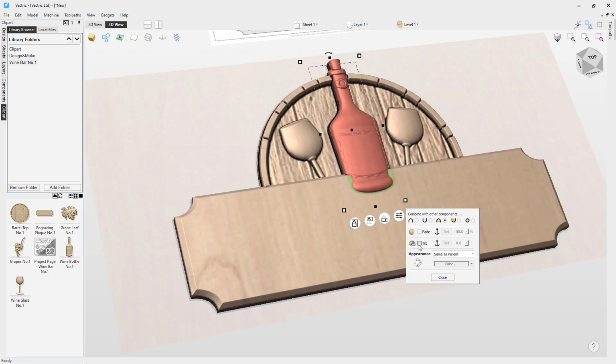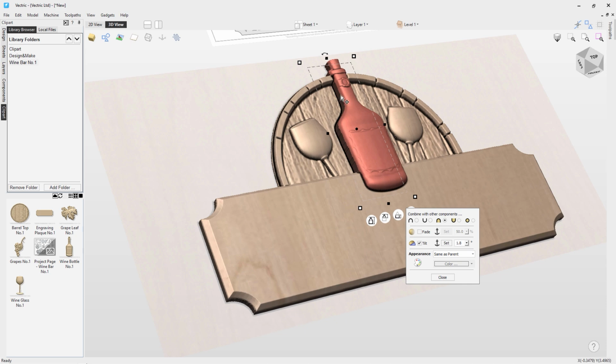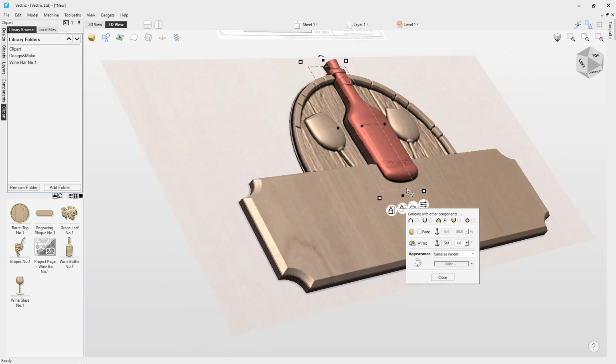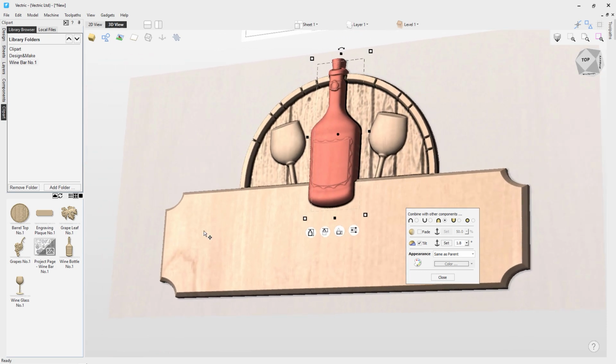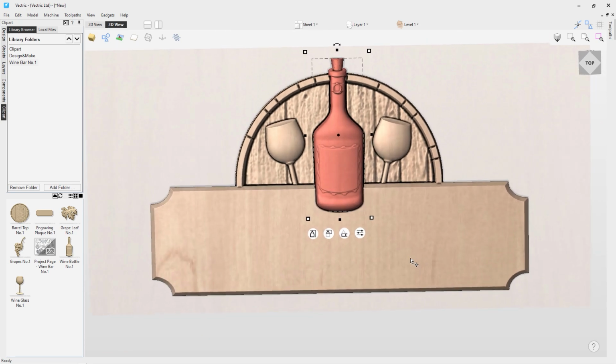And what I'll do is click on tilt. I'm going to set the anchor points. I'm going to set one up here, so you can see the number 1 next to it, indicating that's the first anchor point we're going to access from, and the second point is where we're going to have the high point. Then we can use this slider here to manually adjust the degrees in which we tilt. We can also just set a value here, but you can see how that's tilting it so that I'm still getting the top of it popping through here, but also the bottom end of the wine barrel, so it doesn't look funny from any angle. And I think right there looks pretty good, so I'm just going to close that out, and then we're going to do the same thing for our wine glasses.